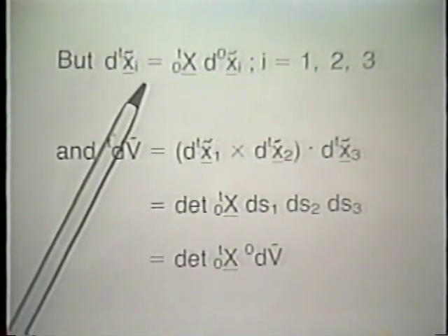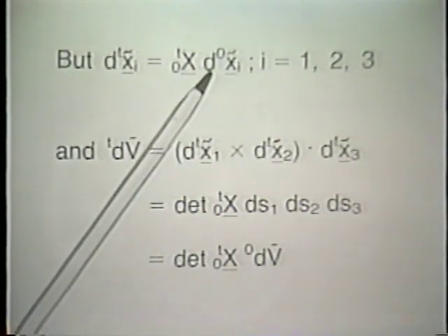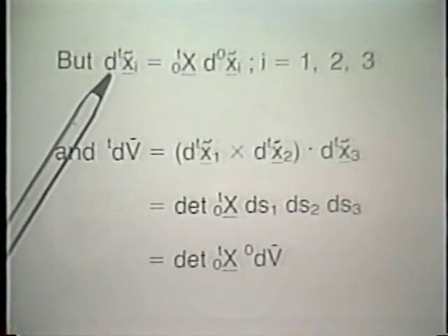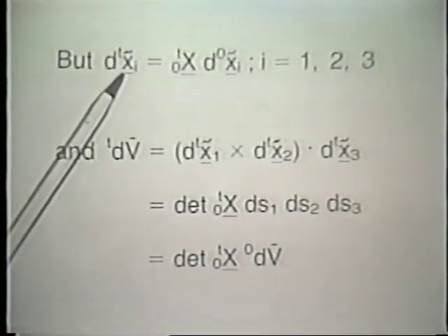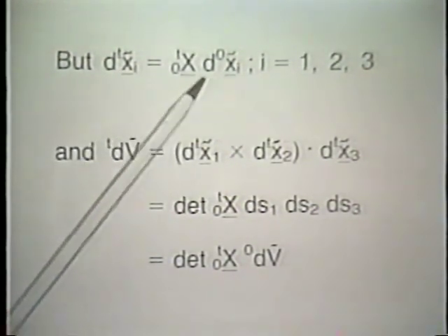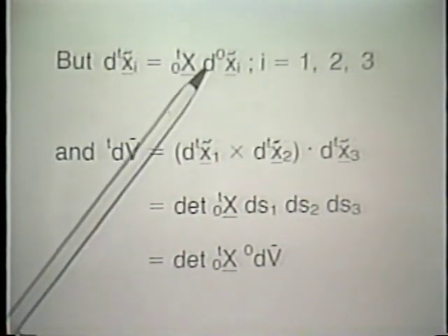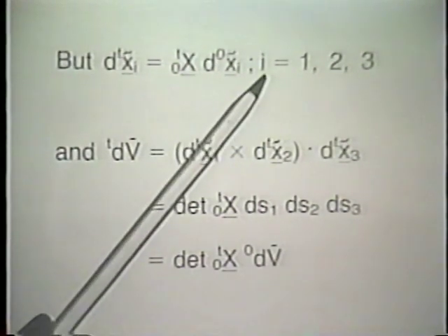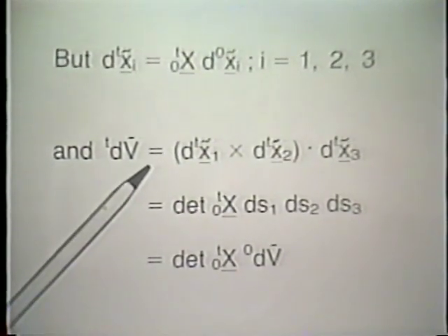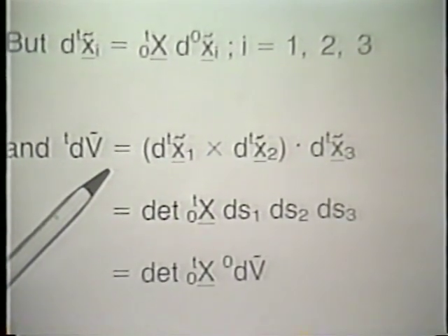We looked already at examples where we put in a particular fiber, original configuration, and calculated how this fiber stretched and deformed from time 0 to time t. I just gave you some examples. And we use that information now here to express the dtx curl I in terms of d0x curl I, of course, for I equals 1 to 3. And now we use here a formula that you must have encountered some time ago in your studies of mathematics.